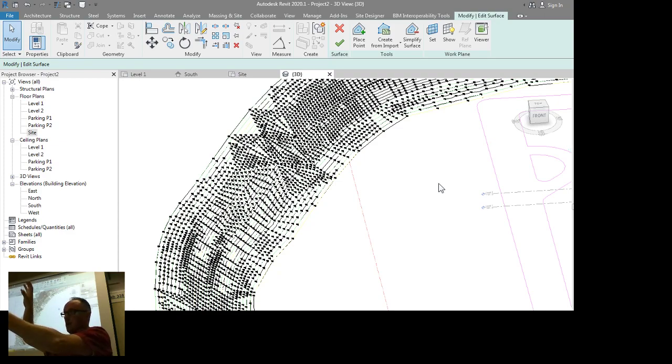And so the rod man, as he's called, will wander around and go to like 200 different locations on the side of the hill there, and they'll turn the laser and shoot it at that prism several hundred times, come back to the office, and the surveyor's software will interpolate between those several hundred points and build all of these contour lines that you get in the survey from your surveyor.